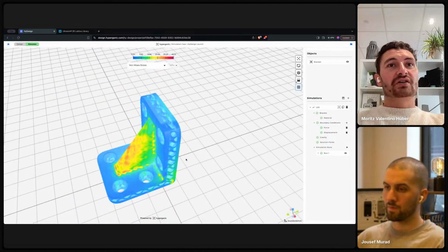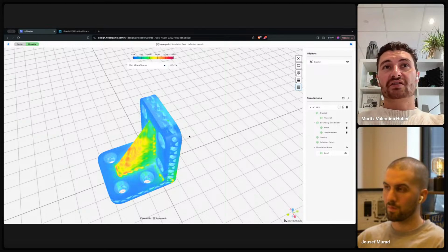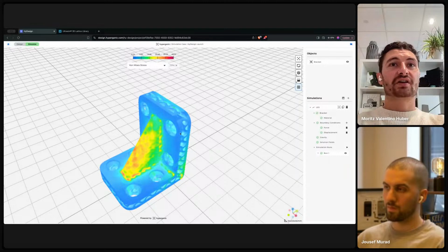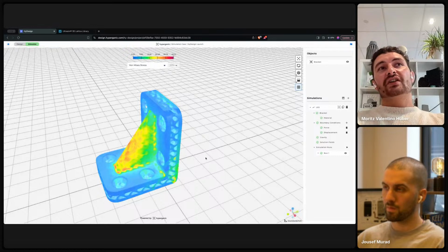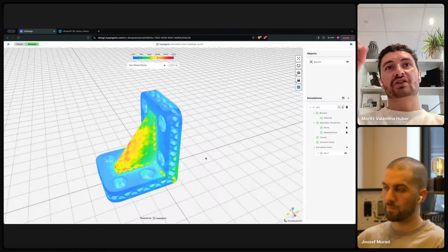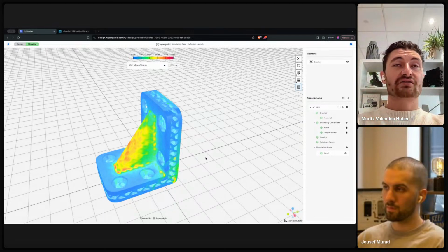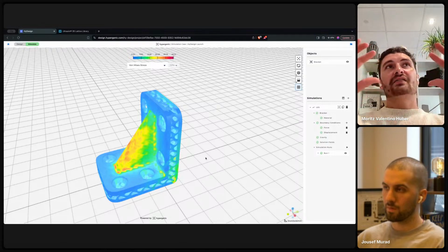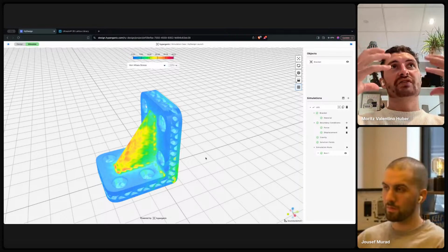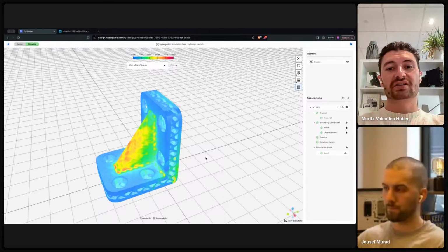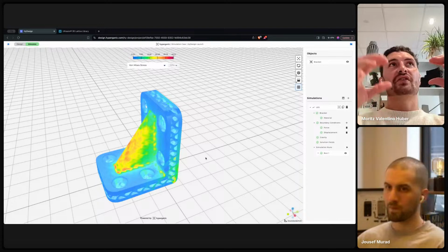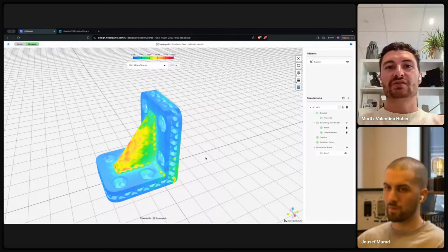So with our immersed boundary method, finite cell method, structural solver for, again, linear elastic static stress strain and thermal conduction, you effectively immerse the geometry into a grid of regular sized or irregular sized hexahedral simulation elements. It's almost like dissolving the object into this pre-existing simulation grid, and then we use the information of which elements are filled with object to simulate these simulation elements.